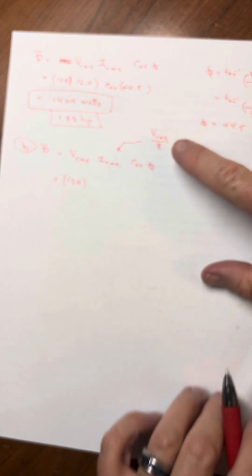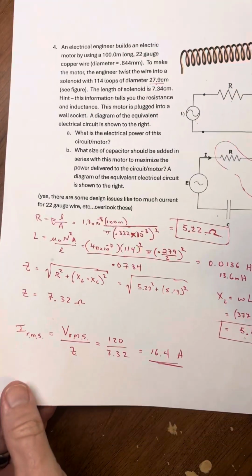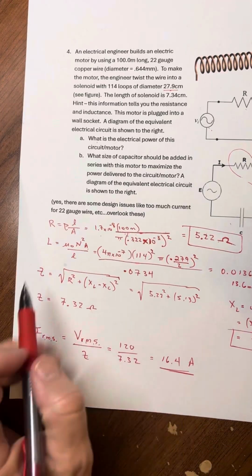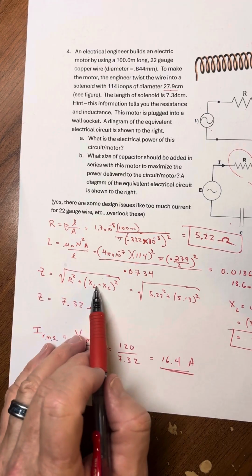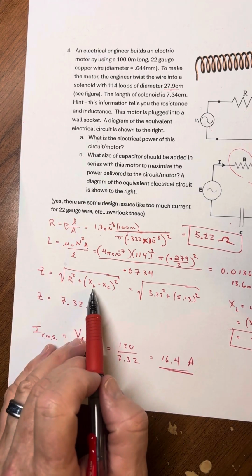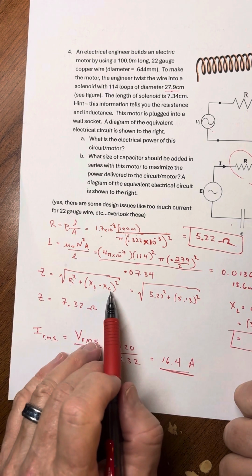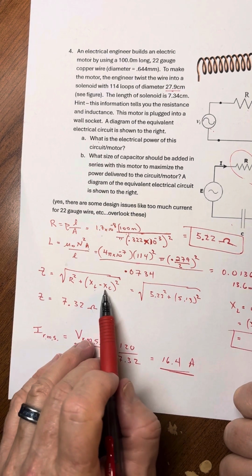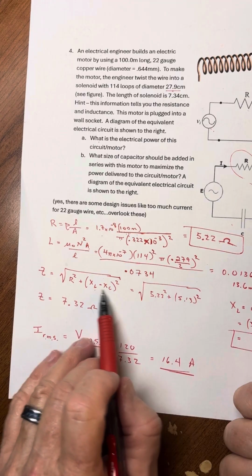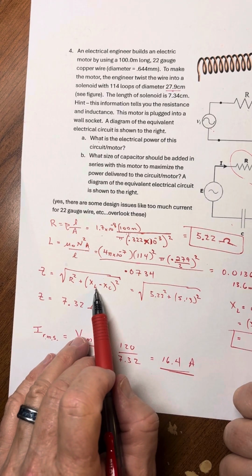And so the smaller you make the impedance, and now you can begin to see, if we can't really change what we already have, the wiring and the loops to make the magnetic field, we could add a capacitor here, balancing off the reactance of the inductor.